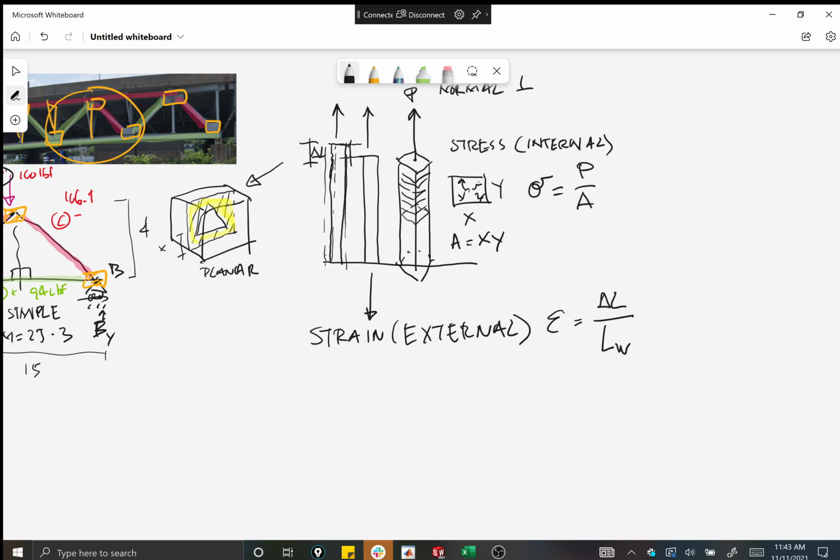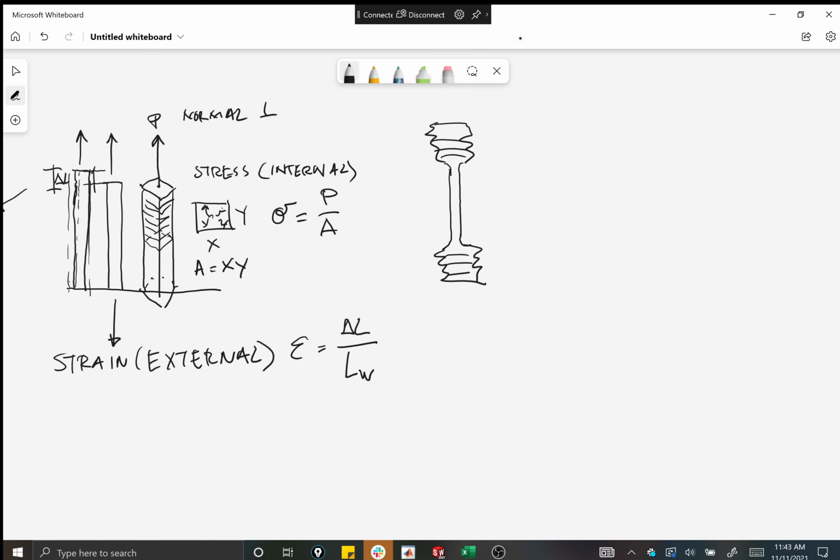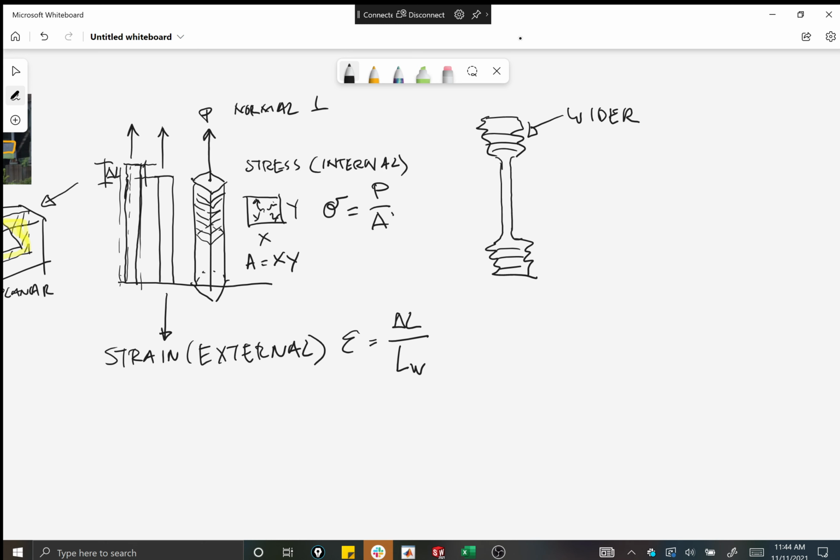Okay, let's dive into this for a second. If this is a specimen in tension, why are the threads wider than the part we're measuring? And why would wider make them not fail? Just call out. The area. If the load is the same and the area is larger, it's going to be stronger because there's going to be less stress on it.